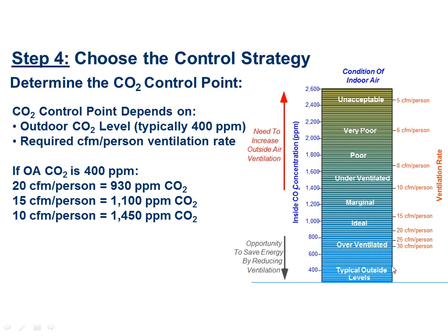It's overventilated. If you get a handheld CO2 meter and walk into any of your customer spaces, chances are fairly good that you'll be able to see one story or the other. Either you're overventilating, which means you're down here at the bottom of the chart and wasting energy when people aren't here, because you're ventilating for design occupancy, which is not happening at the moment. Or you're underventilating your space, which means you're probably going to have IAQ problems and you need to fix something to make sure you get enough outside air.